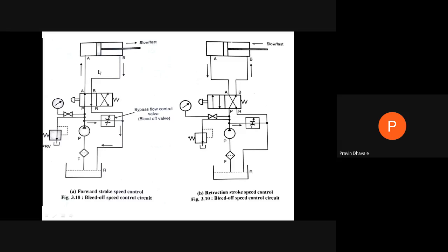To move the piston in the outward direction, we must supply some fluid at the head side of the piston, so some energy has to be supplied. That energy is transferred to the fluid on the right-hand side of the piston. It gets wasted when you supply that fluid directly to the reservoir. If you can utilize the energy of the fluid going to the reservoir, it can be used to move the piston to the right with a higher speed.